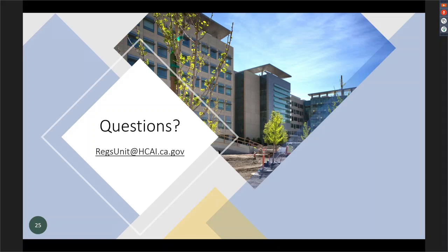So an NMA is a change to the design. It's just not a material change to the design. It is still a change. If it wasn't a change, we don't need to see it. If you're not changing the design, we don't need to see it. So the fact that you're submitting an NMA saying there is a change, but it's considered non-material, still requires a stamp and signature.